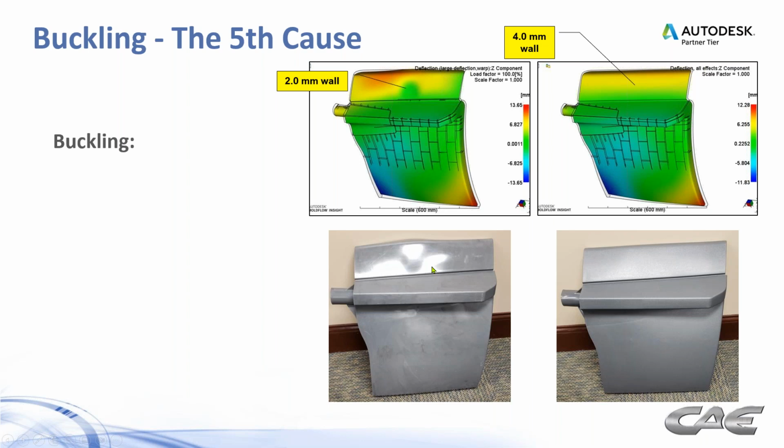So Moldflow gets a bad name, right? No, it's not the software. It was the engineer that worked on it that didn't realize that you have to run buckling analysis sometimes, and I would argue all the time, in order to pick up these types of problems before they become a big headache. So in this case, it was a part design issue that caused the buckling.